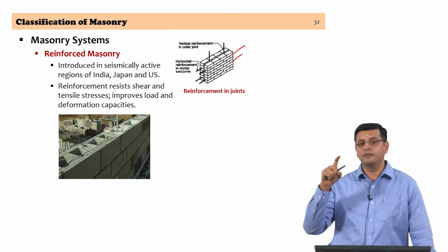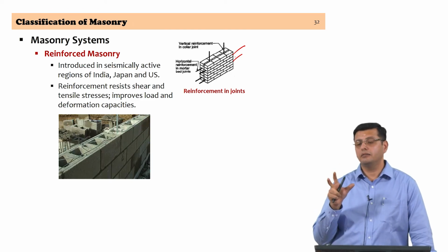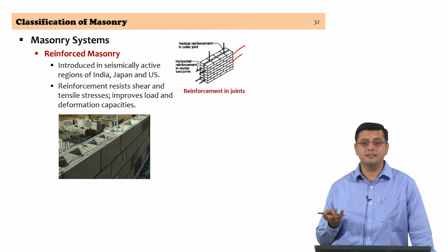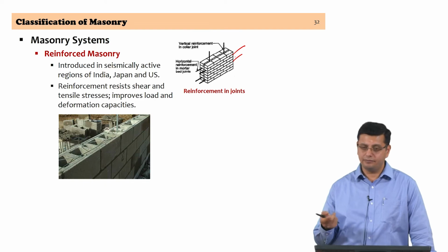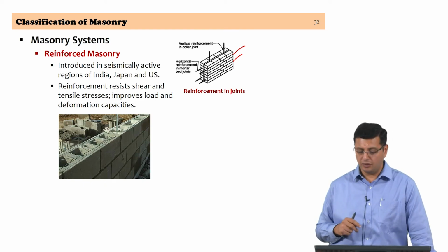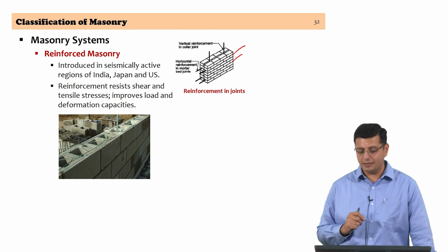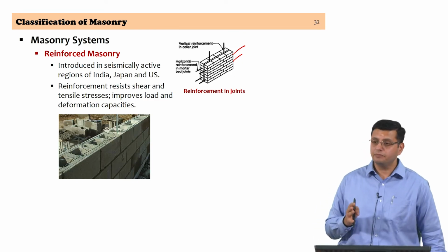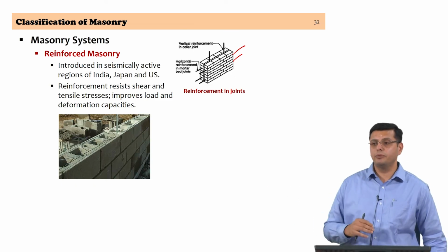And mind you, if it is brickwork, then you are looking at a material which is rather porous and has high water absorption as its characteristic. So, something that absorbs water significantly placed close to steel is definitely not a situation that you want to create, and hence you need a mortar joint that protects the steel reinforcement. So, while this is possible, there are practical difficulties that one has to face in terms of long term durability of such constructions.